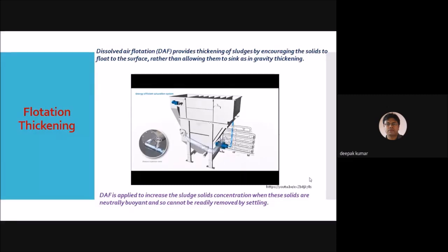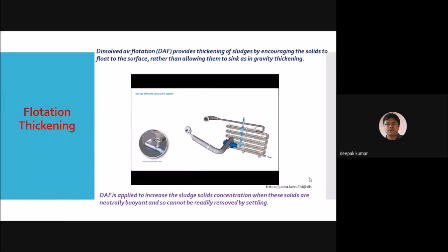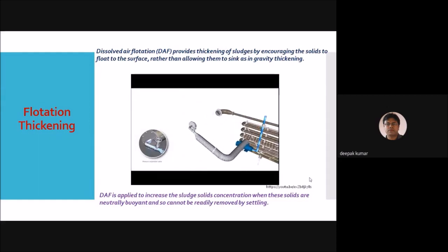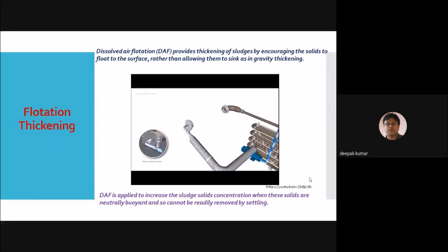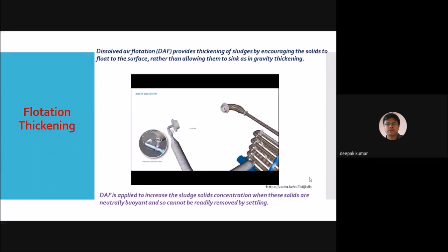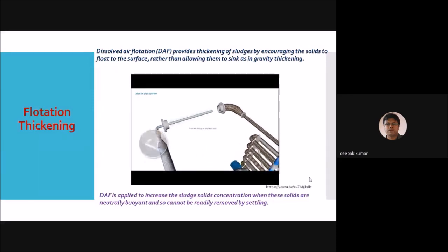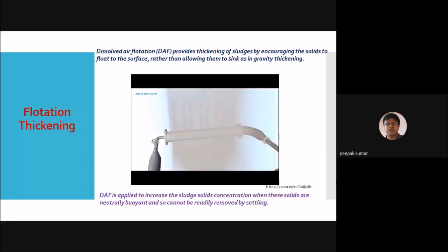We are giving pressurized air to the system. This pressurized air gets mixed with the sludge. This dissolved air flotation is applied to increase the sludge solids concentration.